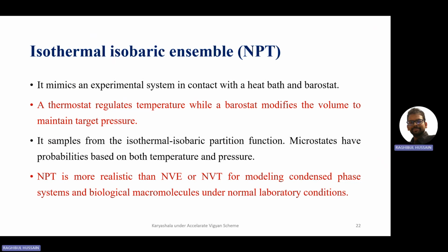Okay. So NPT mimics the experimental system in contact with a heat bath as well as a barostat, where the thermostat regulates the temperature while the barostat modifies the volume to maintain the target pressure. NPT is more realistic than NVE and NVT for modeling condensed phase systems. The physicists say condensed phase, the chemical engineers say liquid phase. That's a fancy term for the physicists. We are working on condensed matter, right?